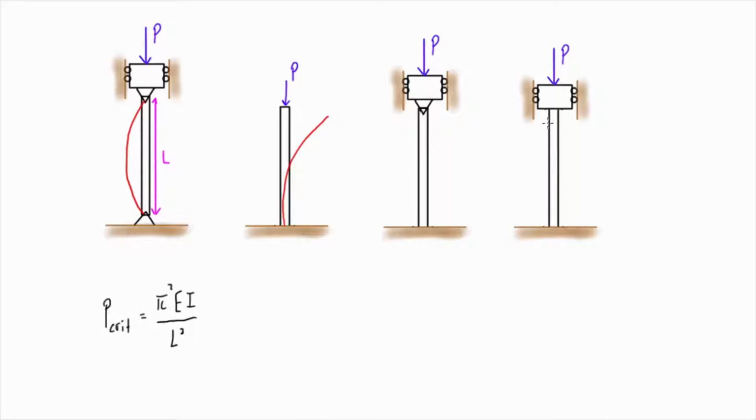In the case of two fixed connections, because even after a deflection the rigid connections stay rigid, we're going to get something, and this is super exaggerated, that comes out straight like that, then there'll be a curve in the middle and it comes back in straight. And if we have a fixed connection on one end, it's going to come out straight like that, but then the pin up here is free to deflect right at the pin. So we end up with some wildly exaggerated deflection just like that. The way that we account for these is we talk about effective length rather than just the actual length of the column.